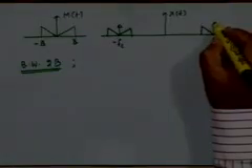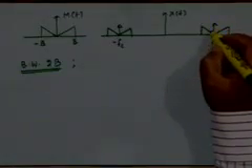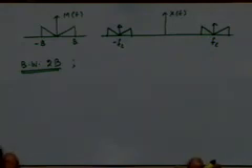It is helpful to us in some other way at the receiver, which we still have to see, but by itself, in as far as our objective is to transmit information, that purpose is not being served by the transmission of the carrier component, right? So in that sense, this spectral component that we are transmitting is actually a waste of power. And therefore, there is a kind of power inefficiency that we have introduced by introducing the carrier component in the transmission process.